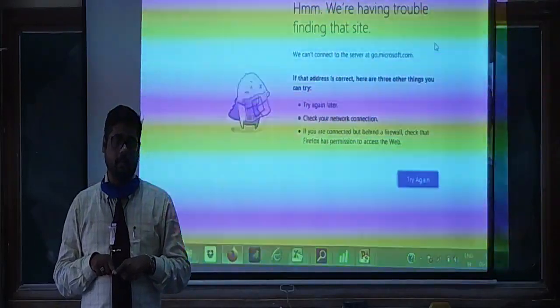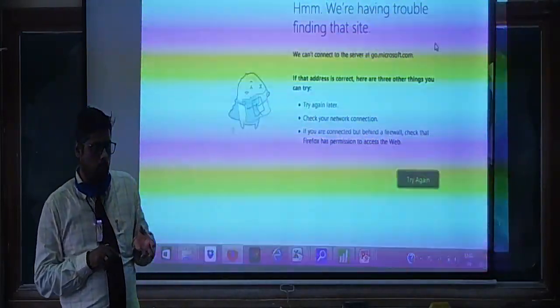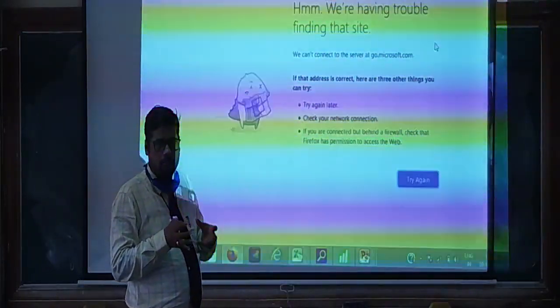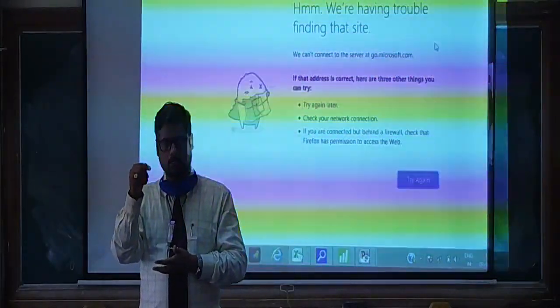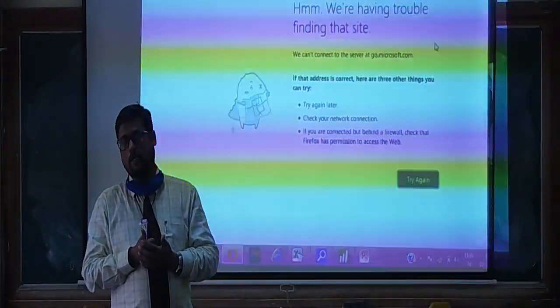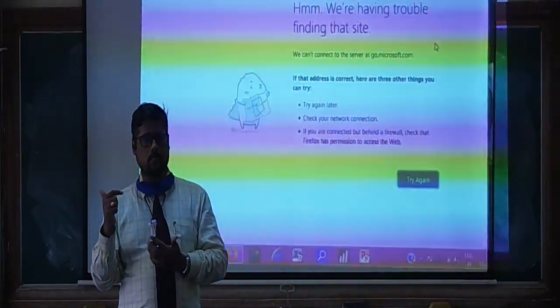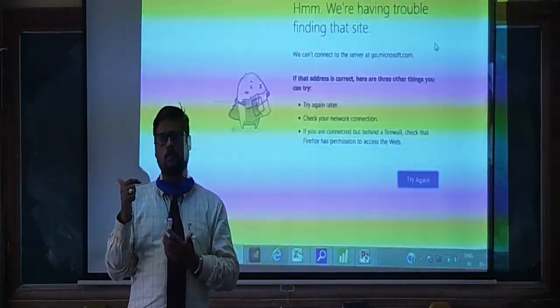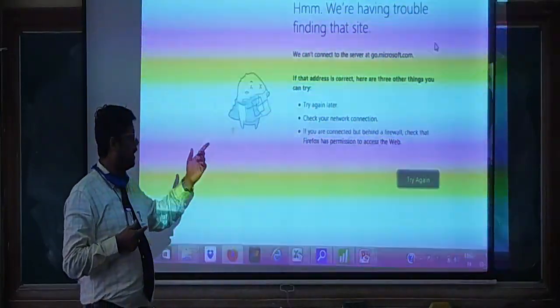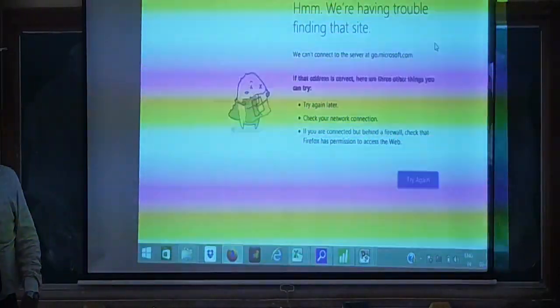In the tolerance band, if the component diameter is given as, say, 100 mm, plus or minus, say plus side it is 0, minus side it is 20 micron or 25 micron or 30 microns.